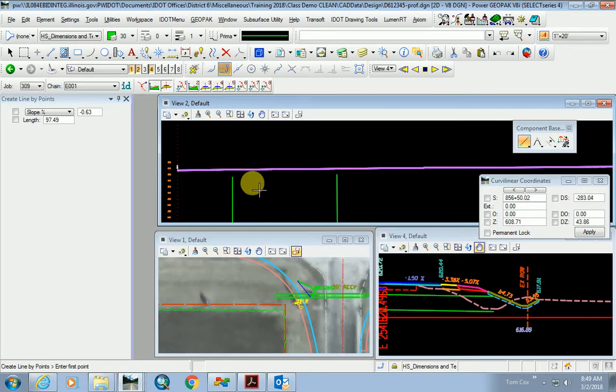Because I know that anything over 3% is going to cause erosion, right? So I go there, and it says 0.66, and I can deal with that. So it would be a done deal. I mean, I'll just go with that. And so then you would need to get that special ditch profile stored into coordinate geometry in some way.